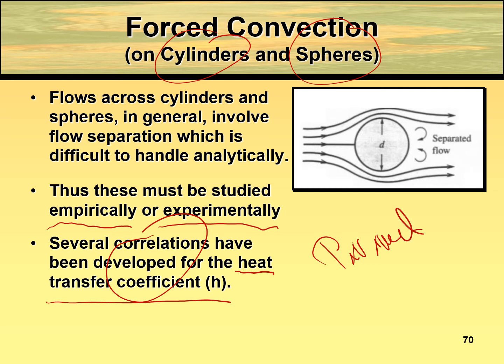Okay, so what kind of parameters? It is the Reynolds number and the Prandtl number. Can you recall the Reynolds number equation, which is rho V L divided by mu, and the Prandtl number, which you can obtain from the properties.